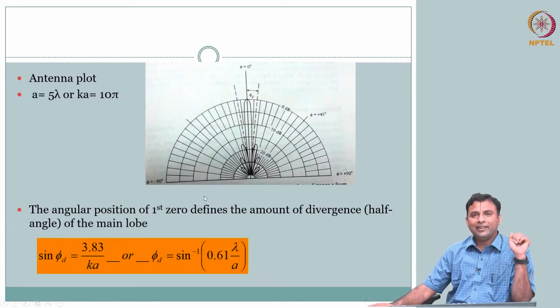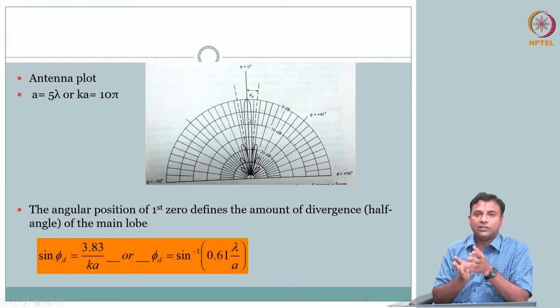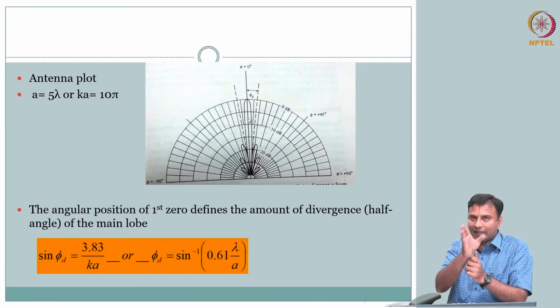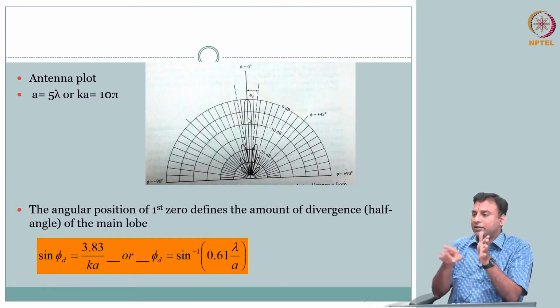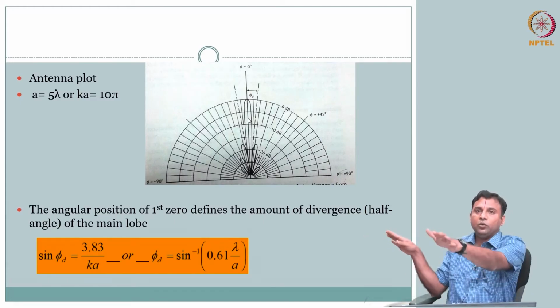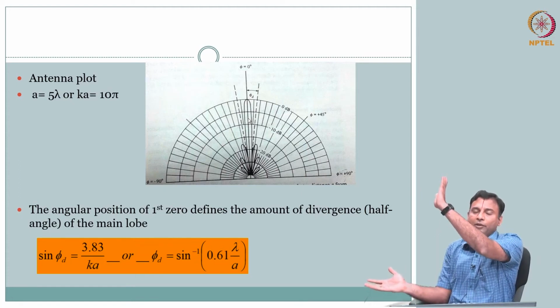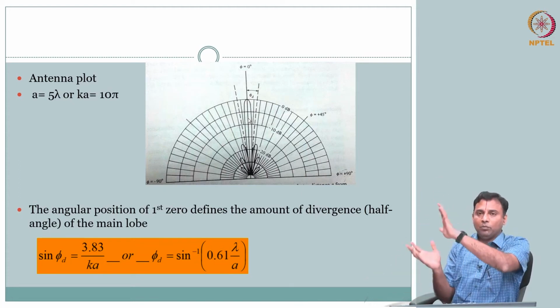So this is another important way of explaining or communicating what we just covered, which is what is called an antenna plot. Typically, because you are talking about divergence, you are talking about angle. 0 will be exactly straight out of the transducer, right? But more importantly, it is not just doing 0, it is spreading out in plane and in elevation, the perpendicular, both.